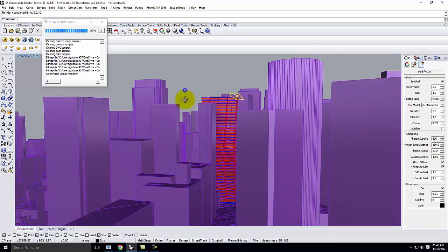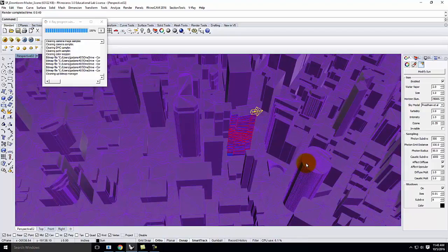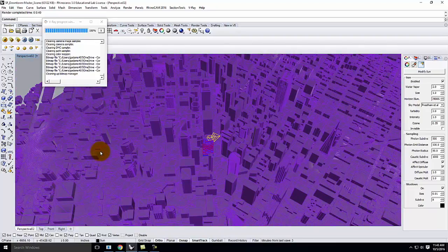And that is that because this can get so chunky, when you have too much data in your file, VRay allows us to create a special object. It's called a VRay Proxy Object, and the VRay Proxy Object basically renders as a whole object, so we see everything, but displays as just a few triangles in Rhino. And so VRay goes and gets the file and adds to it. And it can make working in Rhino much more pleasant. There are two problems with this. Number one, when we make this proxy object, it's completely destructive and will destroy your original object.